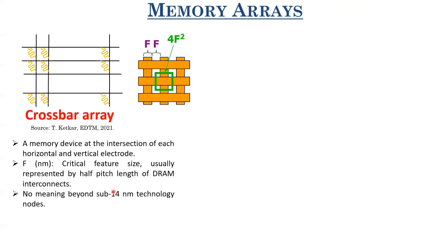This is a concept which you should remember. Nowadays, a reduction in the technology name is just a reduction in the name, not a reduction in the critical size or in any of the features of the chip. Earlier, this was true. Every 1.5 years, the technology node used to go down by a factor of 0.7. Why a factor of 0.7? It's 1 by root 2. Think about it once. And in the discussion session, if possible, let me know why exactly these go down by 0.7. So from 28 nanometer, they'll go down.